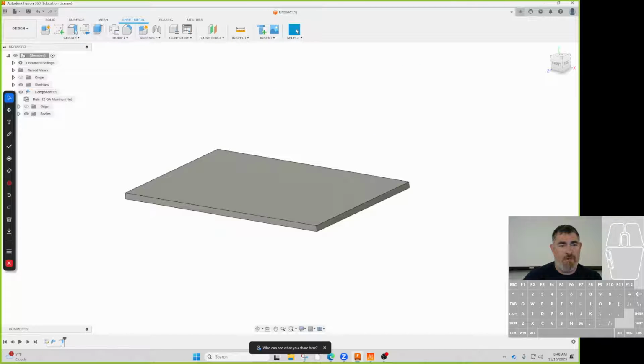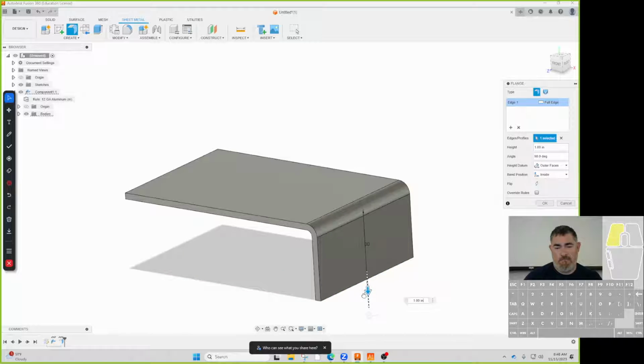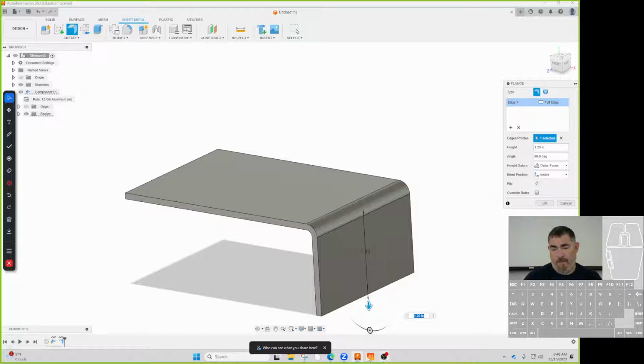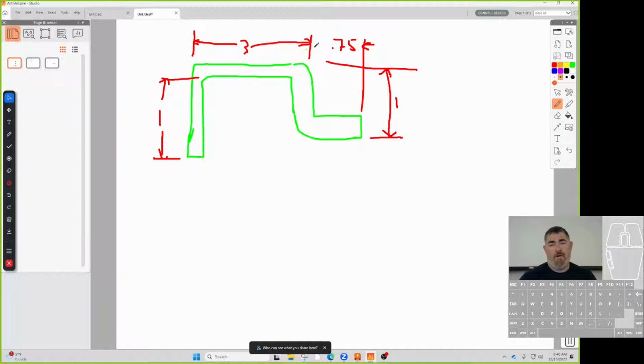And so I'm gonna do my flange, pick here, go down. Where is it aligned? So I always kind of work the alignment first and then the length. So where is it aligned? Is it on the inside or the outside of where my old edge was?